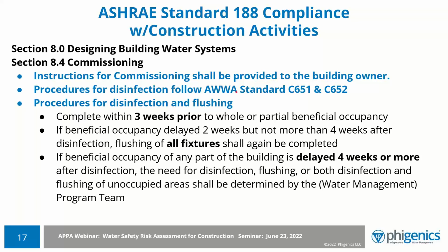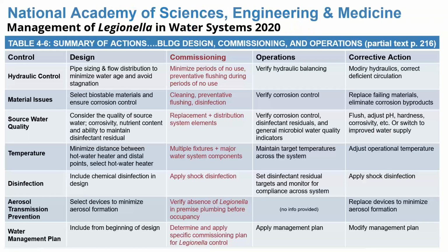You have to understand disinfection standards, and then there is a small procedure written about when you would disinfect and flush prior to occupancy, and there's timing of 3 weeks before, whether you're going to occupy the building or not, and how the water management team would address that. But there's not really a how-to. There's just a very limited amount of information at this point.